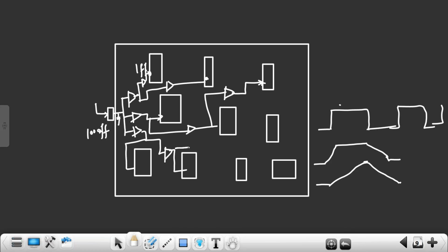So more net length. I should not be having more net length. Even that will also create net capacitance. That net capacitance will become again load for the previous cell. Again use like this. Connect here. Again use one more buffer. Connect here. Connect here. So I have built a tree by using what? Buffers and inverters. So instead of using buffers, I can use what? 2 back-to-back inverters.